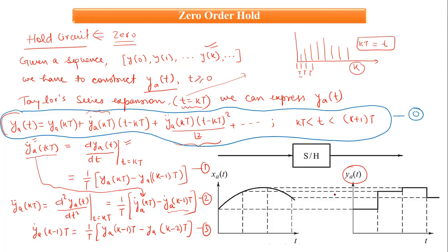Now it is very important, as we have discussed many times in our previous lectures, to have the signal reconstructed in its actual form. So to reconstruct the signal in its actual form, we make use of these hold circuits. Here, this is the actual analog signal which is input, and this is the output. We have these samples, for example.